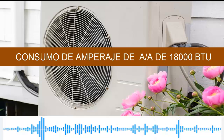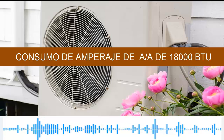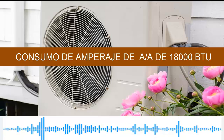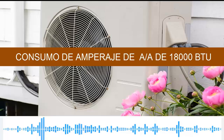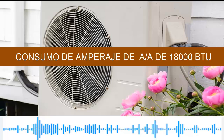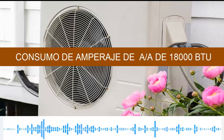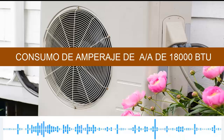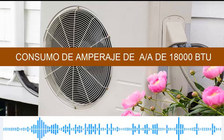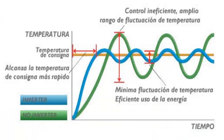Now, let's examine the consumption of the inverter air conditioner when it begins to regulate its electrical consumption. When we talk about an inverter air conditioner, once the desired room temperature is reached, the equipment's compressor has the ability to reduce the motor's revolutions without completely shutting off. During the period when the motor runs at a slower speed, the compressor's current consumption is lower.